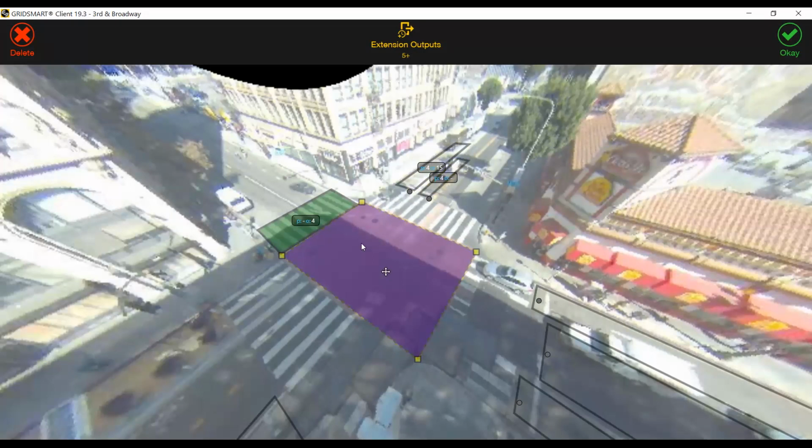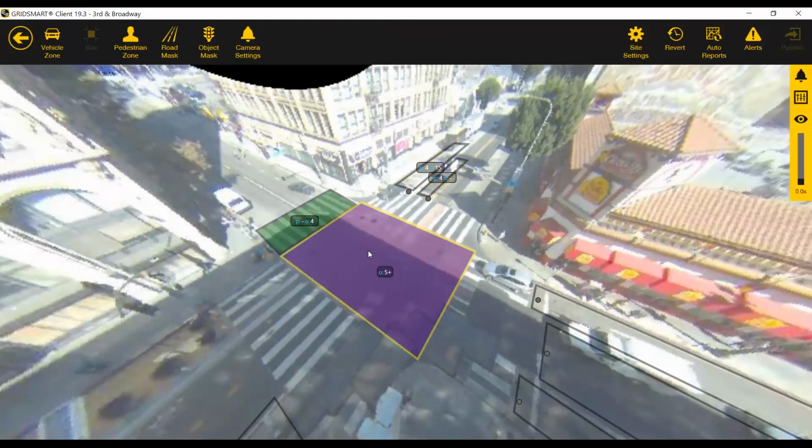It's minimum bike green or no minimum bike green. So our feature goes a step further and provides a bike extension based on its use case, right? If Lance Armstrong is in the left-hand turn pocket and he pushes through in 3 seconds, well, then we drop the call and extend, and we're allowed to be more efficient and move on and service the other cycles. If grandma or grandpa or maybe Sally's following daddy on a left-hand turn and they need more time than the minimum green bike phasing allows on that 14.7 feet per second, they actually need much more time. We can provide that based on their presence.